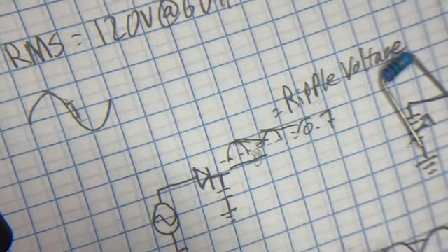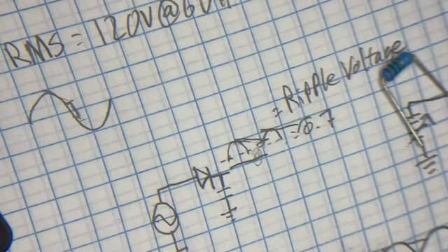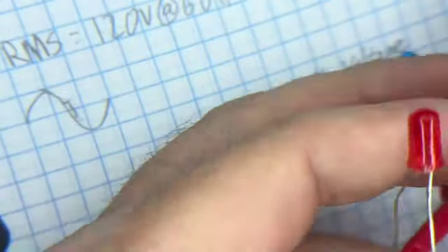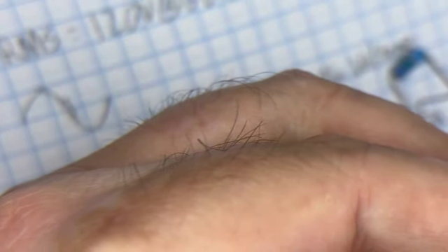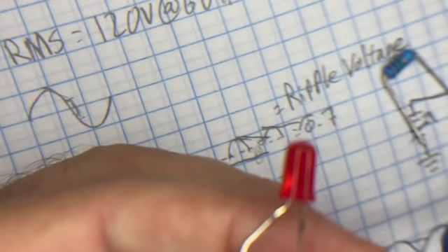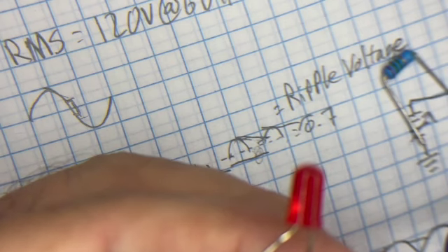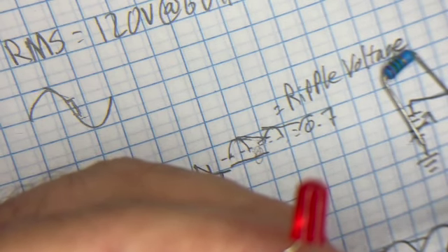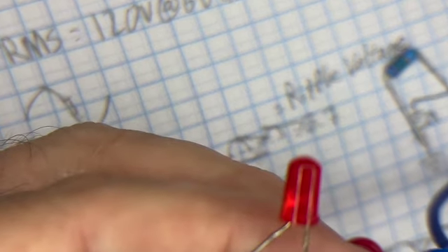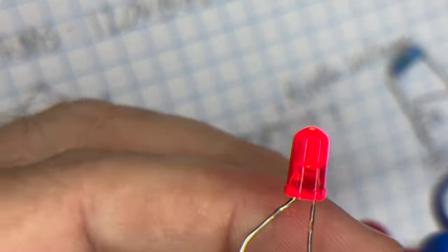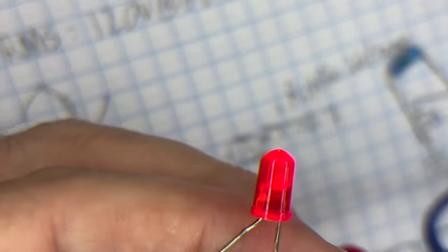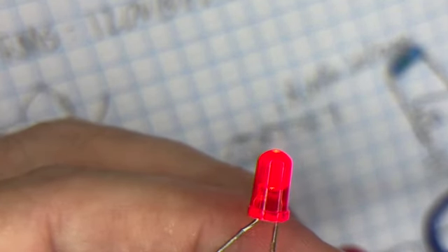Let me see here. I hook up the positive side of my voltage. Hold on, let me get started here. I'm going to turn that down to 0. Hook up my negative side to the cathode. I'm going to slowly turn up the voltage, really slow. I'm at about half a volt, 0.7, 0.8, 1.3, 1.5, 1.8, about 2 volts. Right there, you see it come on? Right there at about 2 volts, it starts coming on. 2.2 volts, and we start seeing light.